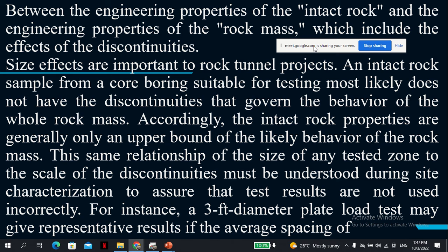So for these reasons, you remember we talked about adits. When you're doing dams, you do adits and pits. So in addition to collecting the samples, depending on the level, for example in a dam, you dig a pit to a depth of at least half of the dam, and if the conditions are worse, in certain selected pits you can go up to the same height of the dam, just so that you have a complete profile and you can pick up things that you might easily miss, like for example the discontinuity.